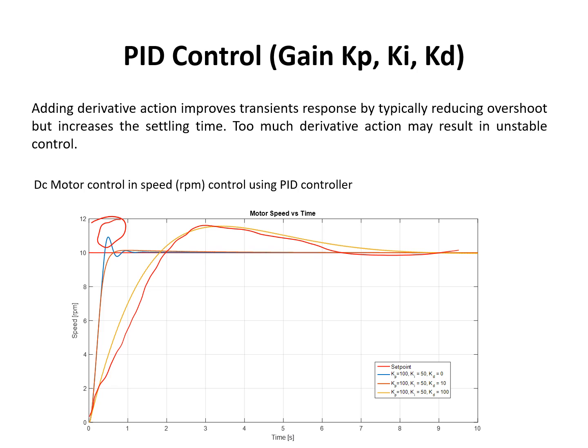In general, if one tunes a controller manually, if you know that you need to add an additional pole to your system to go from a type 0 to a type 1 system, in essence to reduce the steady state error to 0, then you add an integral term. So if you're doing position control, where it's a type 0 system, you don't have to add an additional pole to create a type 1 system to get the error down to 0.